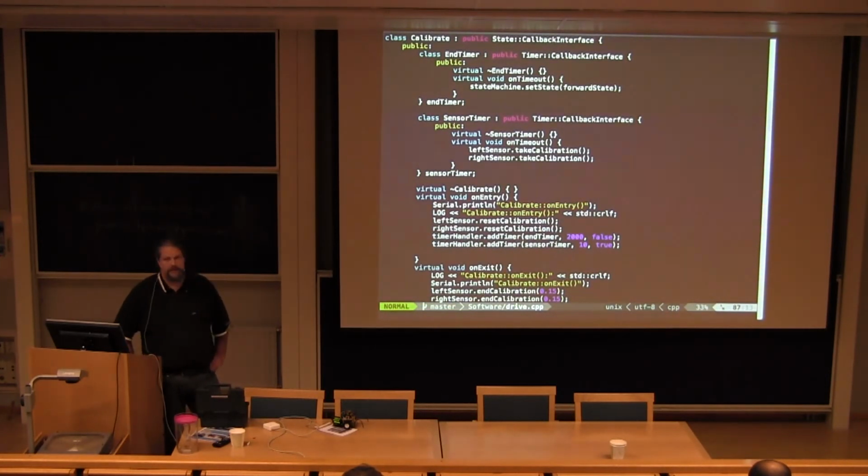You need to communicate out with the Raspberry Pi, probably using an SPI bridge or an I2C bridge, and you need to make controlling stuff that is listening to that I2C or SPI bus, and then you have almost made yourself an Arduino before you get there. We need something like the chip from the Arduino to decode all that. If you are going to make it this simple, you need something like that.